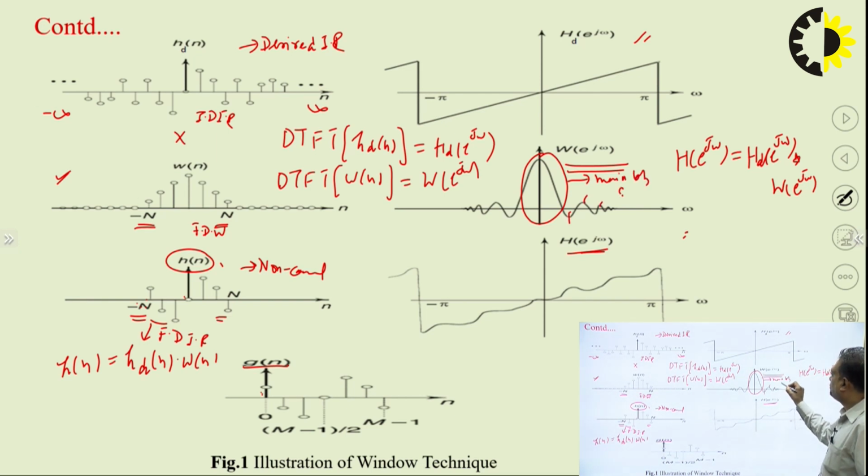So basically what type of frequency response should a window function have? The frequency response should be such that all the energy is concentrated over the main lobe only. There should be no side lobes, or very few side lobes, because side lobes are nothing but spectral leakage. An ideal window function should be like an impulse, where all the energy is concentrated in an impulse and there are no side lobes.